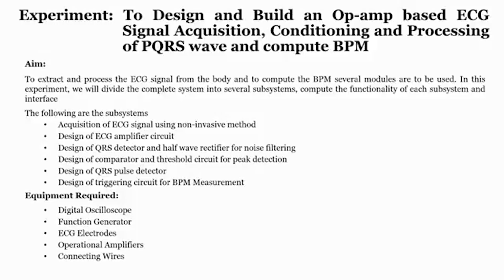We have to always take a difference between two sources. That means we require differentiation, and since the signal to noise ratio is really poor in the acquisition of a raw ECG signal, we require a proper signal conditioning circuit which can improve the signal to noise ratio, and also a filtering circuit to remove the unwanted signals available in the ECG signal. So, to remove them, we should understand what the unwanted signals are and why they are coming into the ECG signal.